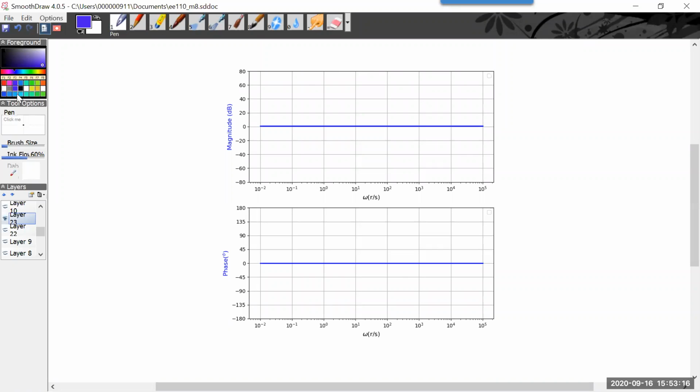Now really, we start off at 40 dB, right? We just draw that kind of straight across. Now you can try to find where something will be equal to 0 dB and then do the slope, but really go to the first pole, the first breakpoint, which is here, right? From here, it's going to go down 20 dB per decade.